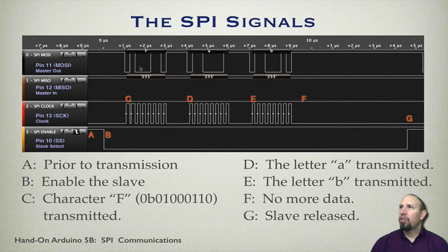And so these are actually those bits. So notice the first bit is 0, then a 1, then 3 zeros. It's hard to see that, but that's actually the length of 3 zeros. Then 2 ones, so that's the length of 2 ones, and then a 0. And then the clock ceases. And so when all 8 of those bits are transmitted, then the interrupt flag is set, indicating that a transmission is complete.